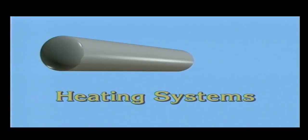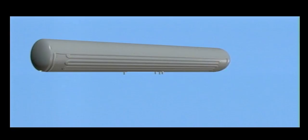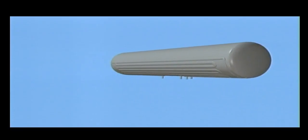Many commodities transported by rail must be heated for unloading when they reach their final destination. This is accomplished by the use of heater coils, the most common being the exterior serpentine system. Coils of this type are generally constructed of half-oval sections welded directly to the tank shell. They typically use steam or hot oil to heat the tank, which in turn heats the commodity.